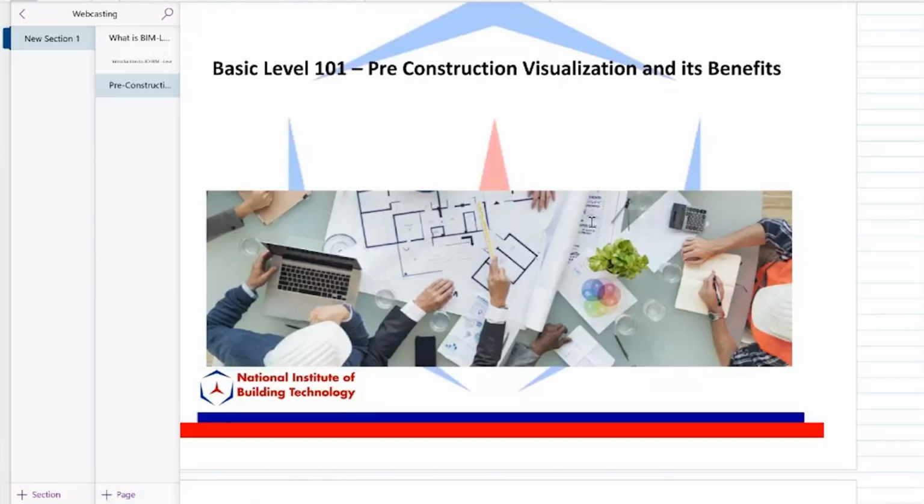So a mechanical contractor will submit his shop drawings, and all these shop drawings will go to the architect and their consultants. And at that point, they will start overlaying these drawings to make sure everything fits. If you have done decent large scale projects, you'll realize this is the process. They will start putting it in place. Then the architect will start thinking, okay, where do I put this thing? So this doesn't work, that doesn't work. They'll start moving things around, designing and things along those lines.